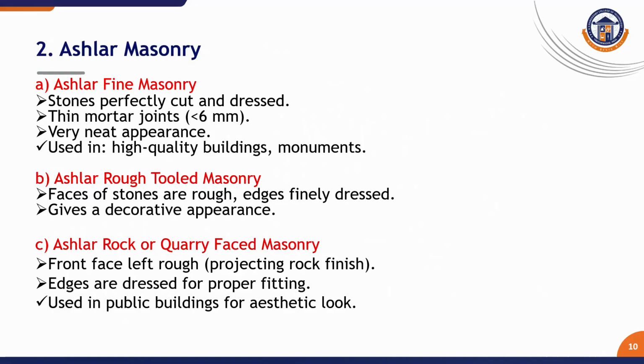Ashlar fine masonry is perfectly cut and dressed, and thin mortar joints are used. It has a very neat appearance compared with ashlar rough tooled masonry. And in ashlar rock or quarry faced masonry, edges are dressed for proper fittings. Used in public buildings for aesthetic look.